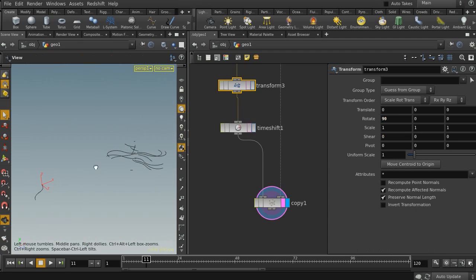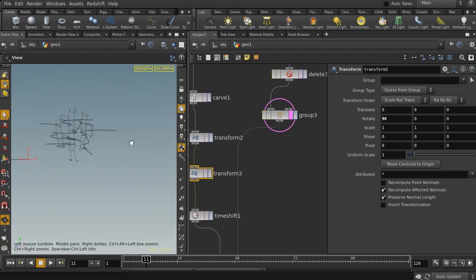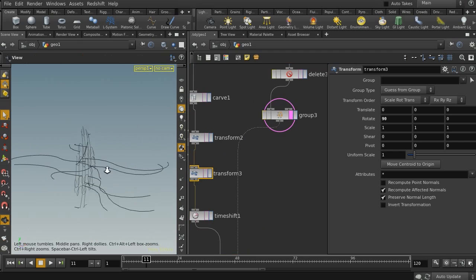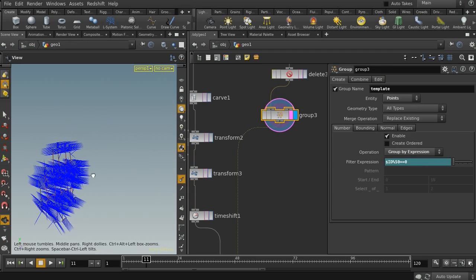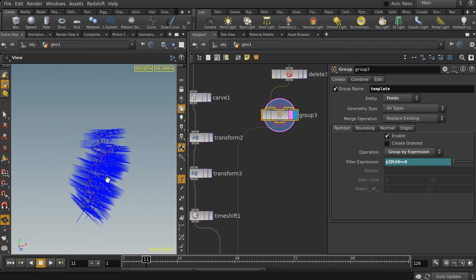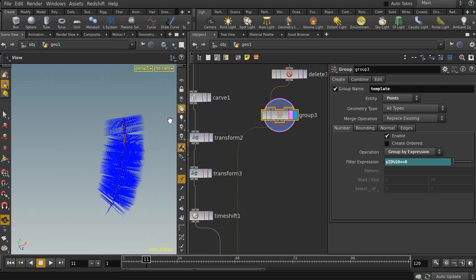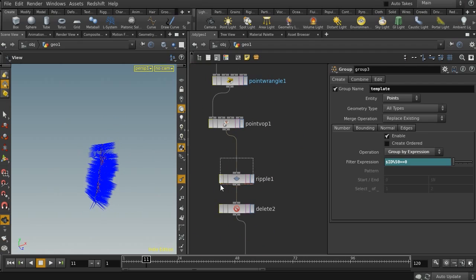And here, as you can see, the normal attribute for the points for the geometry actually is not correct, and as you can see, some of them are toward inside the geometry and some of them are pointing outward the geometry. So the problem is this Repel node.